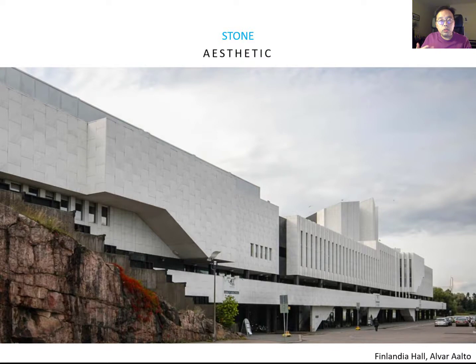Also, natural stone has been used for facade application for centuries. Marble facade in historical buildings has a 4-inch to 8-inch thickness. It's very thick. That was the panel they used for cladding in the historical age. However, nowadays we cannot use a 4-inch to 8-inch thick stone panel, because we have to be concerned about the price and the efficiency. From this reason, we have to use very thin marble cuts for cladding.